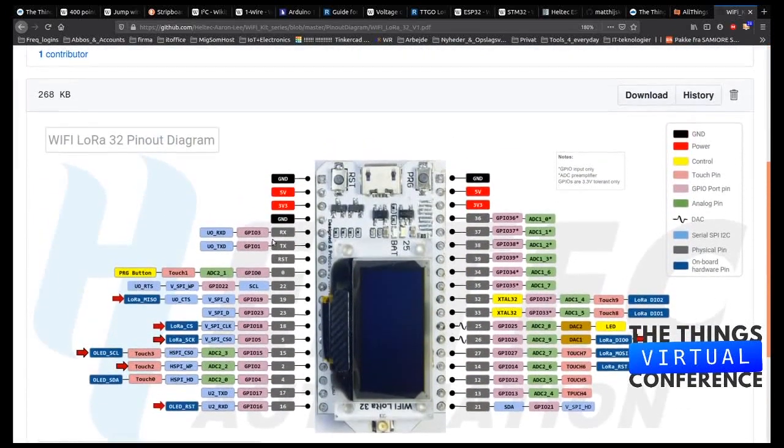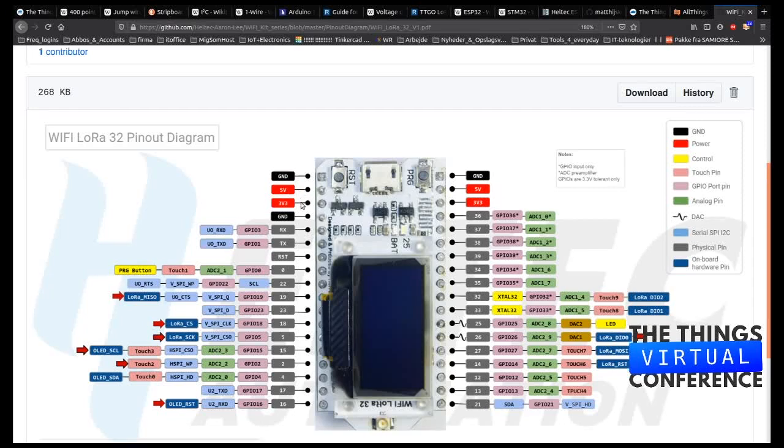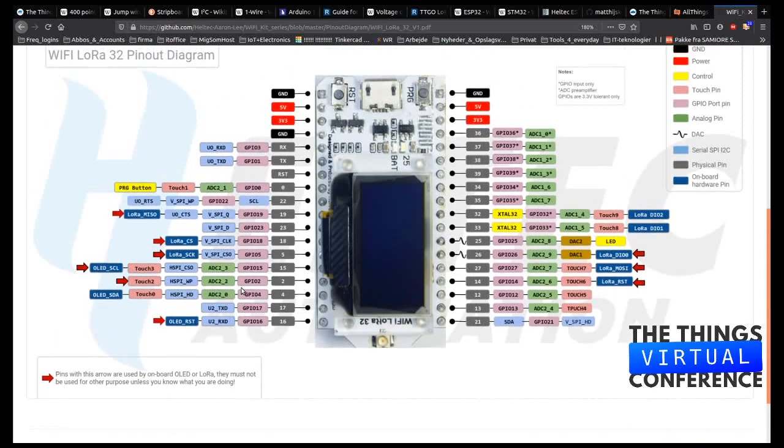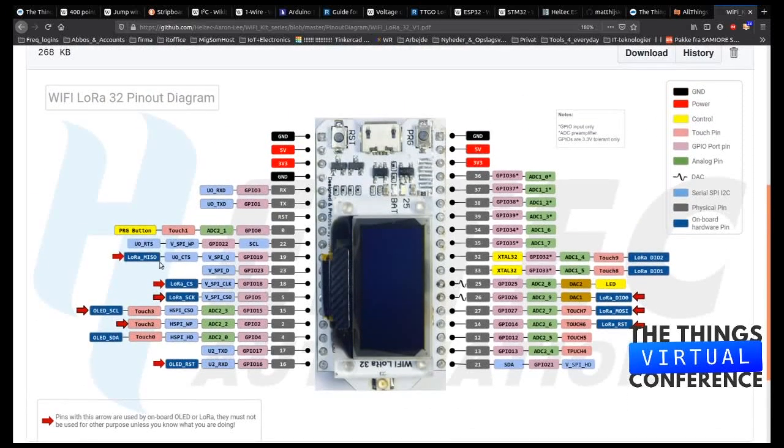And here I can find the pin out, and ground is the first one, 5 volt is the second one, so I actually want that on the third one, 3.3 volt. And then I can find the SCL, that is the I2C. Where are we? Okay, we will use these two.